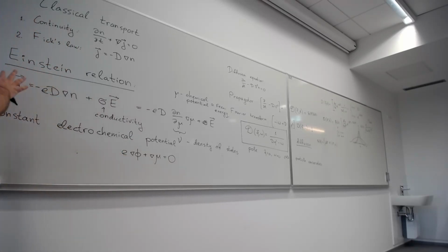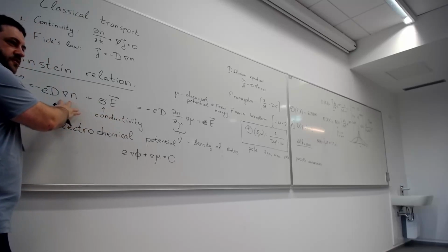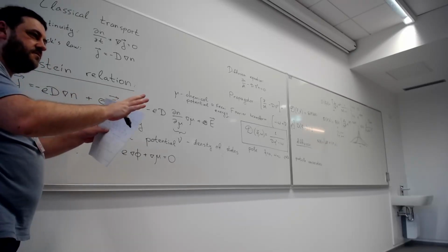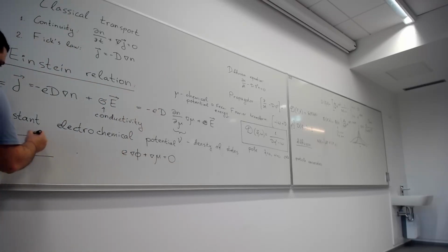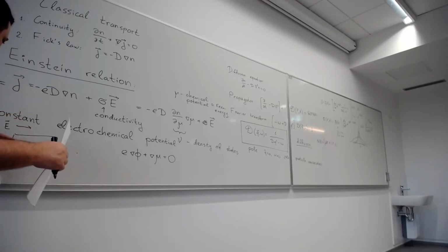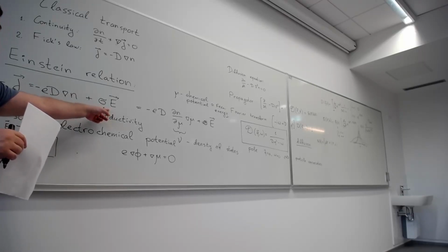Okay, so once again, we have a situation where the electric field created some gradient of concentration. Just imagine we have a piece of metal, we apply an electric field. The current starts flowing, and then there is a wall, the electrons cannot go any further, so a gradient of concentration is created here, such that these two things compensate.